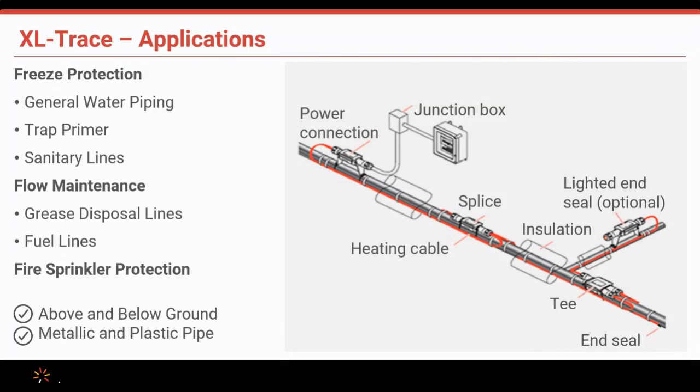Flow maintenance, so anytime you're looking at maintaining a higher temperature, so greasy waste is an example, we like to design and maintain for 110 degrees versus freeze protection, which would just be at 40. So that makes a big difference on how many watts per foot is required.